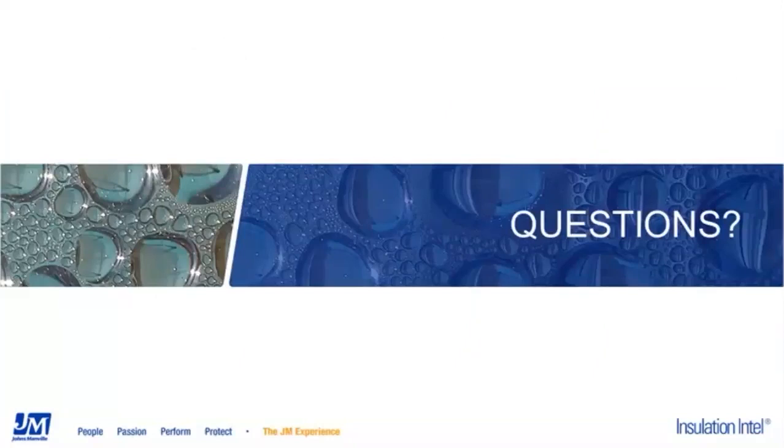I'll start with you, Meredith: how water resistant is the insulation being installed on exterior equipment? That's really going to depend on what type of insulation you're using. We mentioned in the presentation that closed cell insulations have the benefit of being more water resistant, and I can let Jim elaborate a little bit more on that.